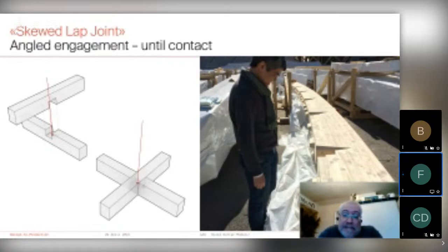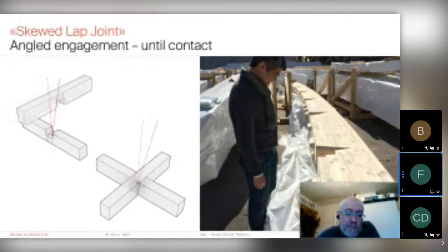So you couldn't use a standard lap joint to do that, and we had to invent pretty early on a solution for this grid shell that would allow us to keep the idea of having those double lap joints, but on curved beams. And the idea is to have what we call the skewed lap joint, where there's a few corners missing. And now you see why the cutouts on the right-hand beam in the image look so strange.